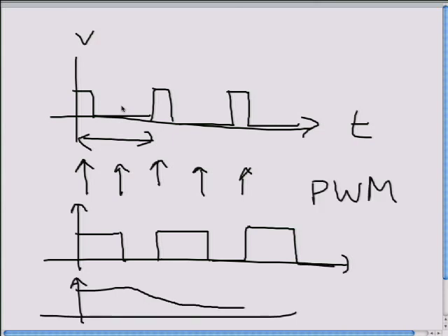Sometimes? I mean, you have to overcome the inertia of the motor. That's true. In motors, actually, their response to voltage is not linear. In particular, if they're still, you have to overcome a static friction to get them going in the first place, right? So it's not a completely linear response. So that's one issue. But let's suppose that you're in a linear operating mode. So the motor is already turning, and its behavior is approximately linear. Then you can, in fact, control the speed of the motor by controlling the voltage that you deliver.